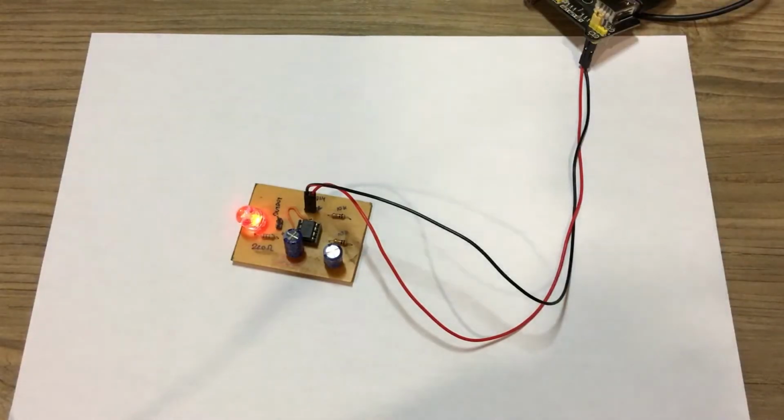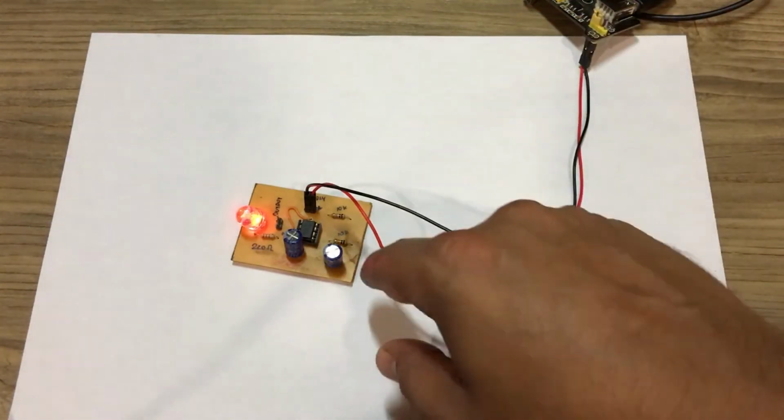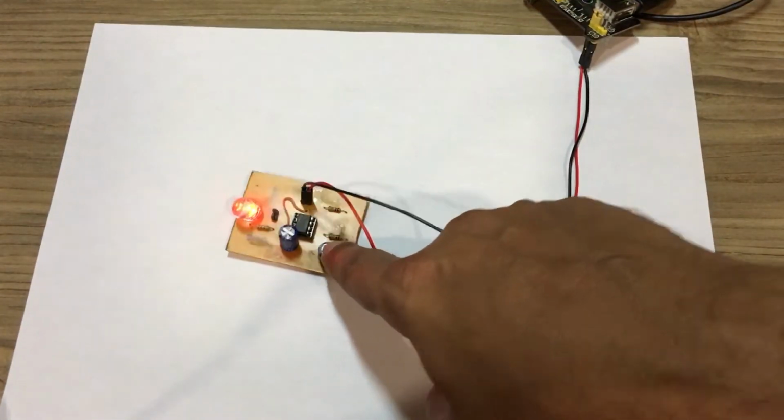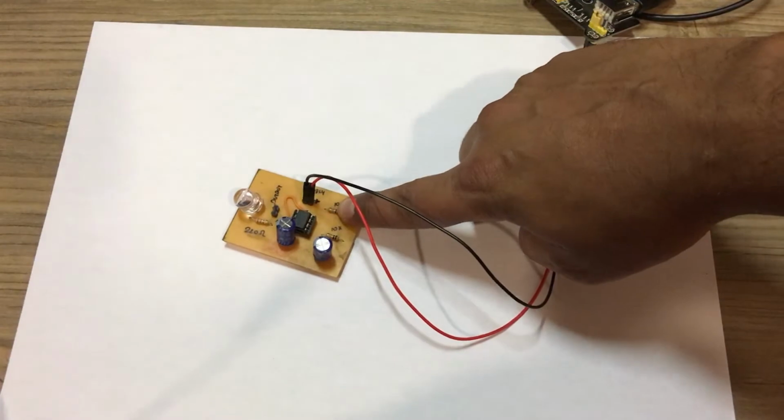Here we are looking at the board which implements the 555 timer in an astable mode. If you look at the board, what it is doing right now is the output of the 555 timer is toggling between the 1 and the 0 state, the on and the off state, which can be seen by the blinking of the LED light over here. The frequency at which it blinks, the amount of time that it's going to remain on for and the amount of time that it's going to remain off for, is determined by the capacitance value which is used over here and the 2 resistances that are there on the board.